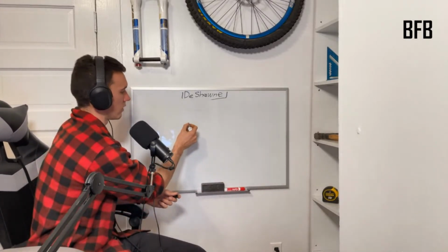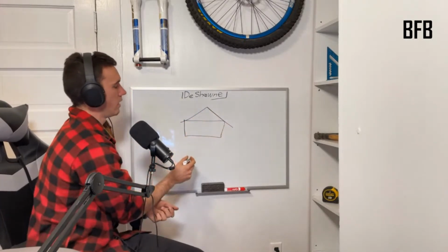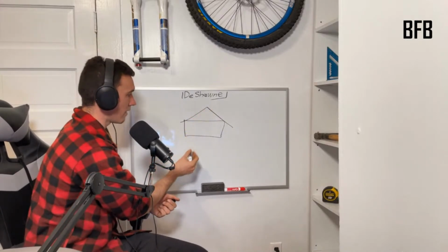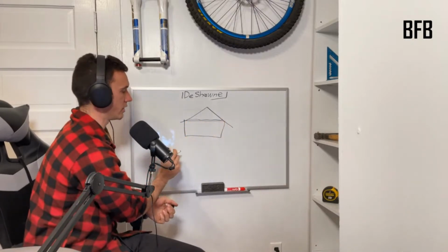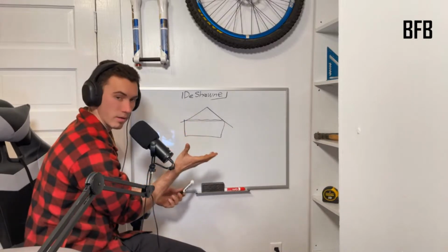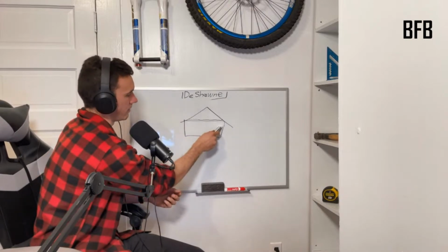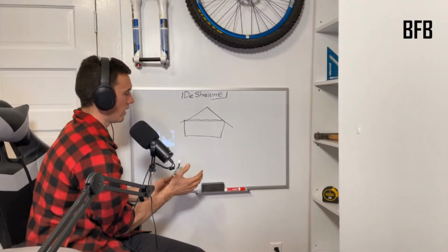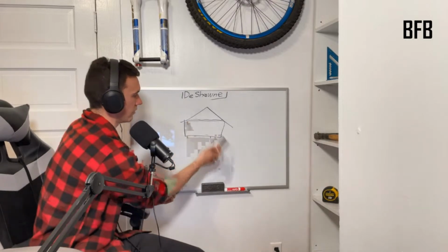So if I have a regular house, like so, with a gable, and I've got a regular, let's say, 8-foot ceiling in here, and then I've got an attic up on top. So what I've got is a whole bunch of ceiling joists going across here, like that, probably in that direction. So when the wind comes and hits this building, it's going to push on this whole area, and it's going to push on this whole area. These are both flat areas. And what we are concerned with is the ceiling diaphragm.